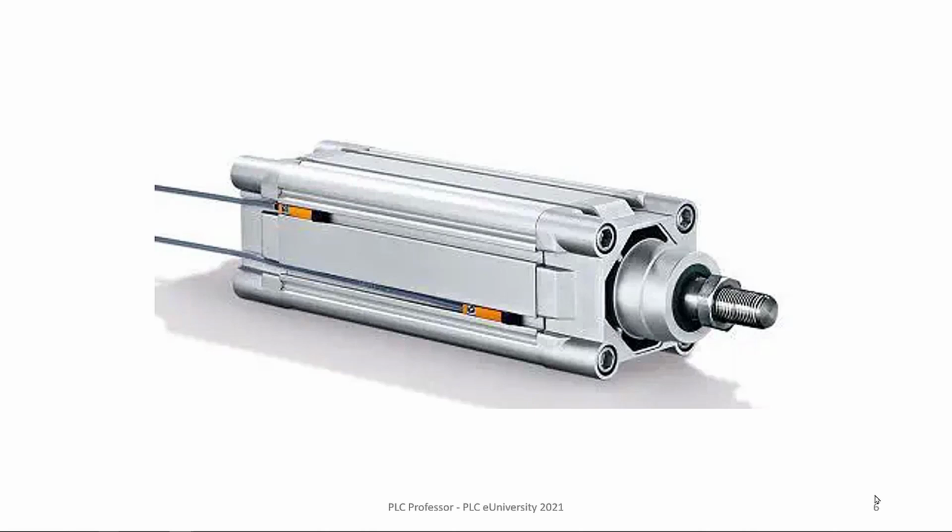Keep in mind that there is some hysteresis in this adjustment. You would not want to move the piston all the way to the rear, retract it, and then push the sensor forward until it just misses or just catches. You want to give a little bit more space than that, because there is some hysteresis.